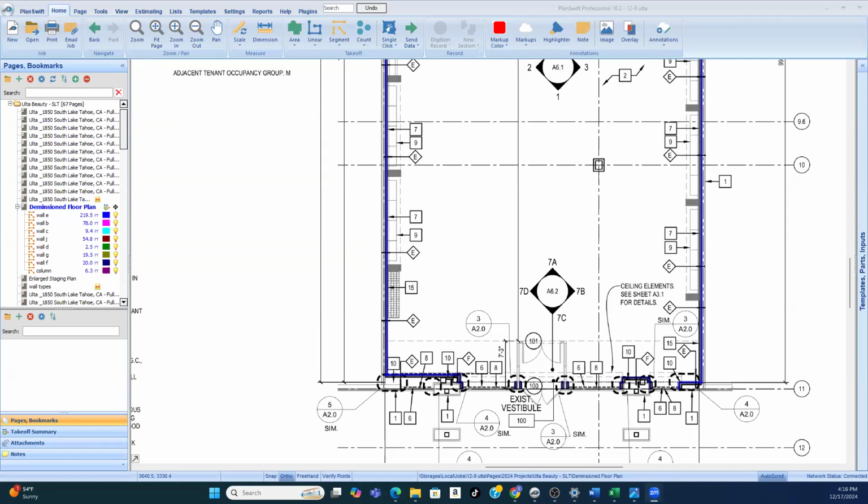For A plans, you'll have the drywall, framing, paint, insulation, roofing, depending on the ceiling, because the ACT, acoustical ceiling tile, if it's commercial, most drywall folks don't do that. So you have to have that one separately. All of your finishes, finished carpentry should be separate. Exterior finishes should be separate. You should know your exterior paint from your interior paint and break all of that down. All of that's in your A plan.